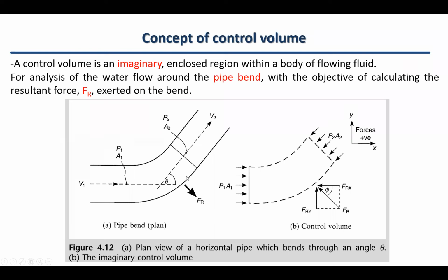This support could be metallic, steel or concrete structures, to make sure that the pipe is not going to move. Because with concrete pipelines, this kicking can cause damage, or even cause the pipeline to burst. So we have to make sure to stop this kicking and the movement under the pressure.